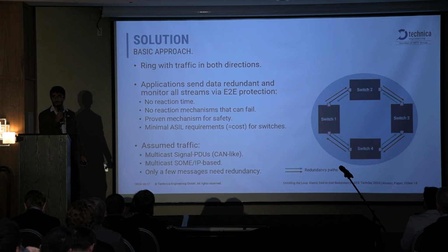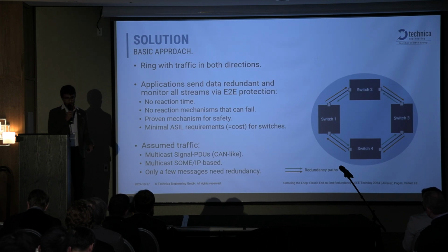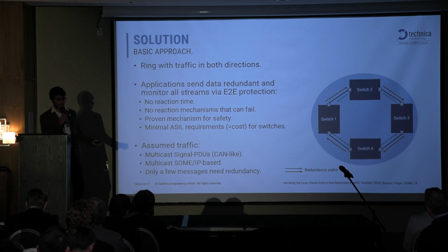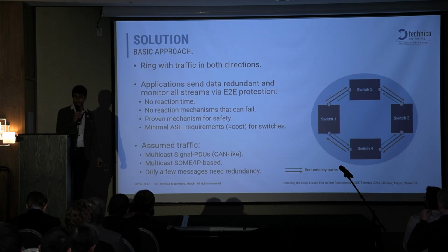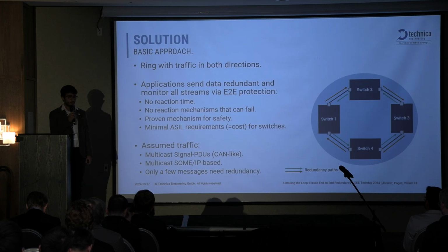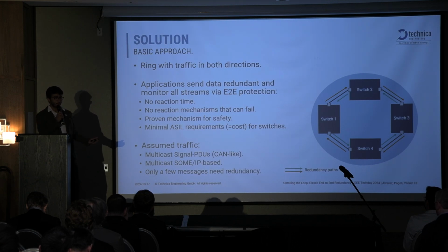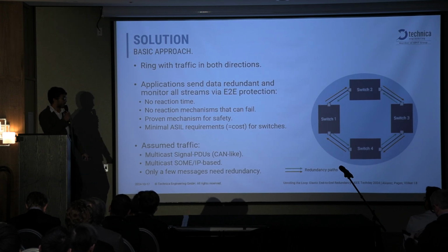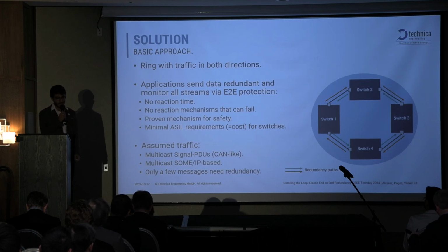How are we trying to benefit from this approach? Well, first of all, we want to create a proactive system. That means, like Lars said, we will have no reaction time whatsoever. And at the same time, there will be no reaction mechanism that can lead into failure. This solution is also a proven mechanism for safety via this end-to-end protection, and due to its simplicity, we will require minimal ASIL requirements that will therefore, of course, imply no additional cost for the switches. It is also important to remark that for this proof of concept, the assumed traffic is multicast traffic, either some IP-based or signal PDU-based multicast.